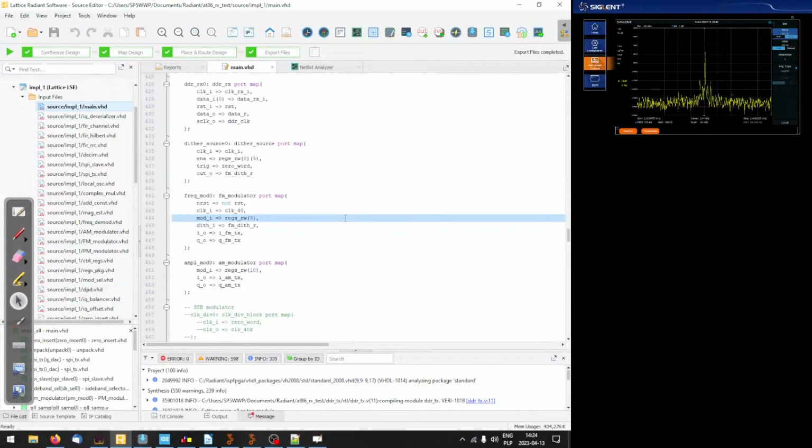So normally you set the squelch level to some threshold, and you can't hear anything below it. If the signal is too weak, you are not going to pick it up. And if the signal is strong enough to reach the threshold, the signal from the demodulator makes its way to the speaker. So that's how the signal strength based squelch works.